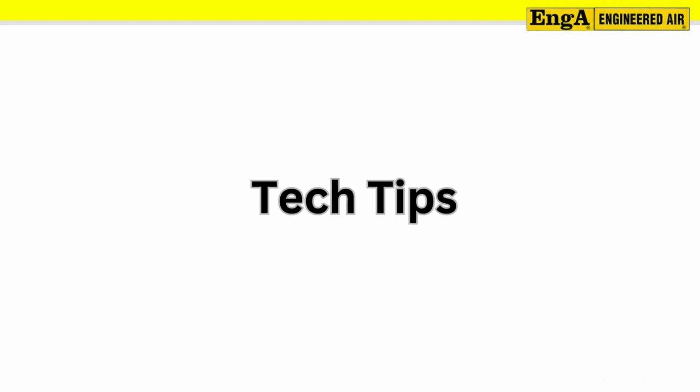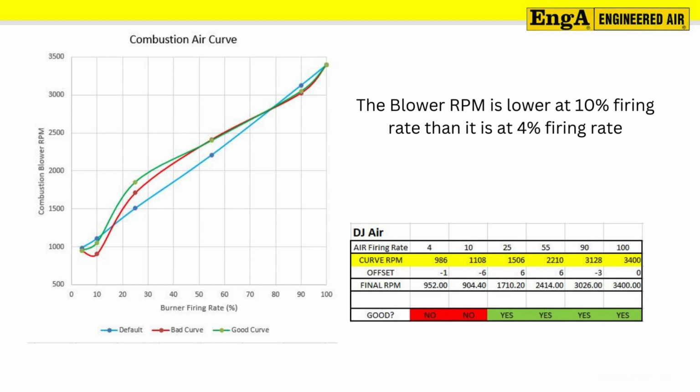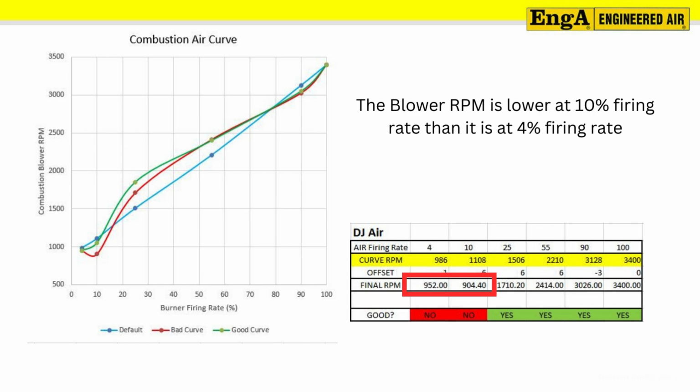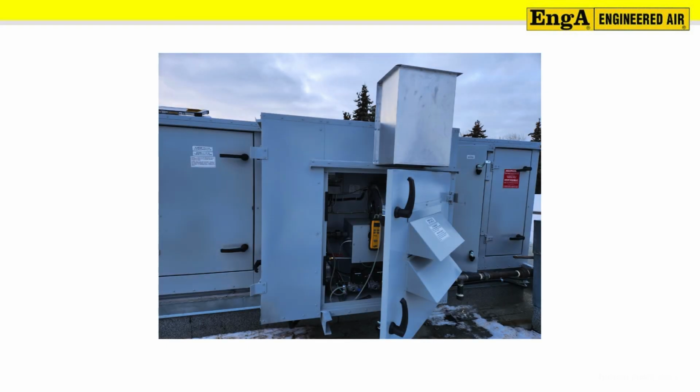Some things to watch out for when completing a combustion setup. When increasing or decreasing the combustion offsets, take note of where the RPM and milliamp signal was on the previous firing rate. It's important not to have these firing rates cross over, or it could cause poor combustion. Record any combustion analyzer measurements with the combustion cabinet door closed. This will reduce any oxygen spikes from wind gusts.